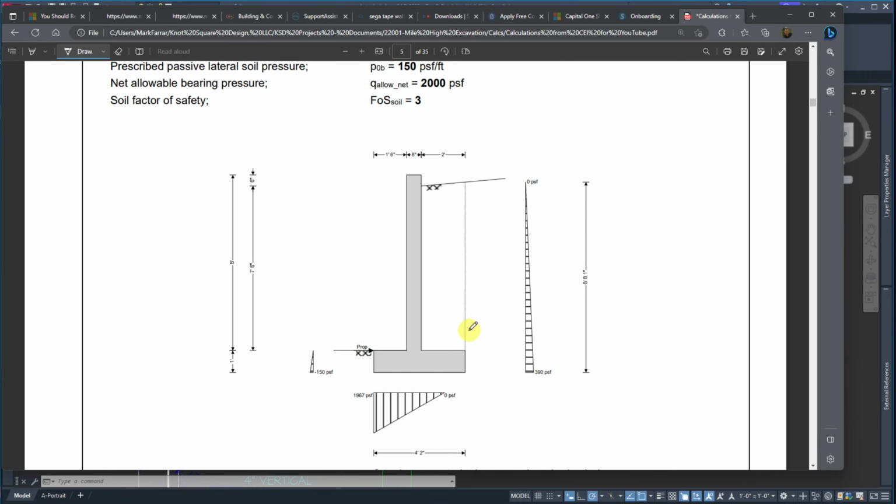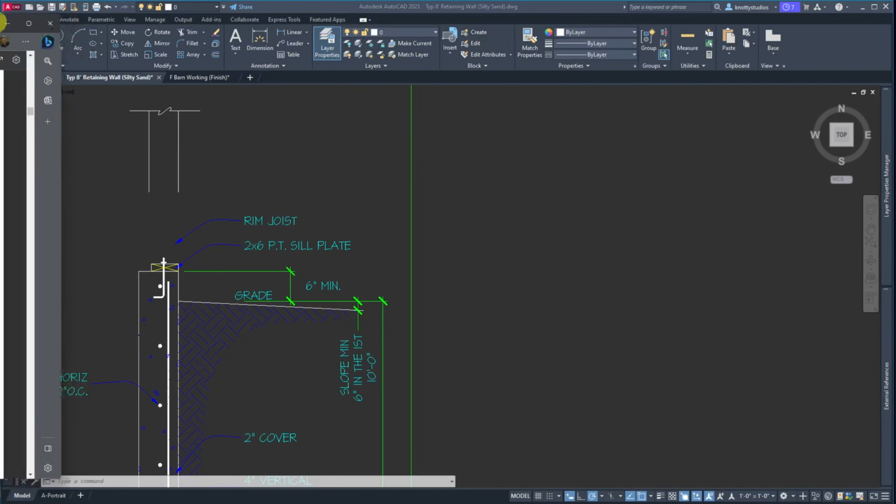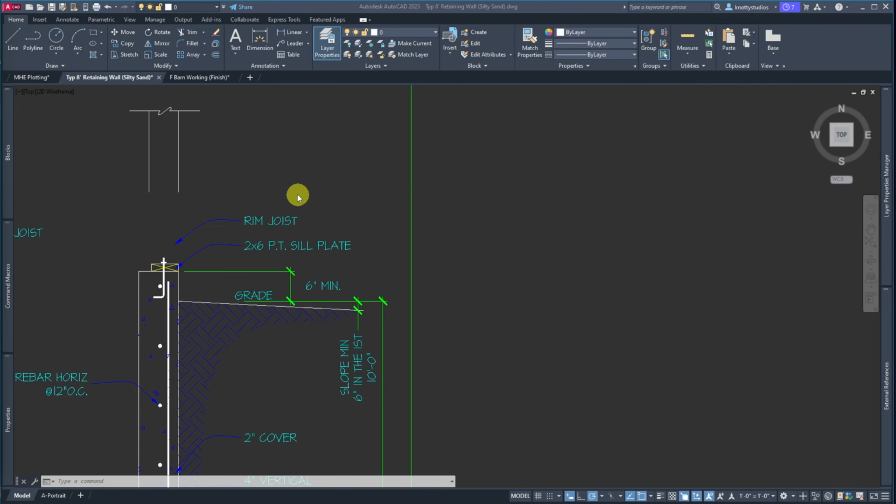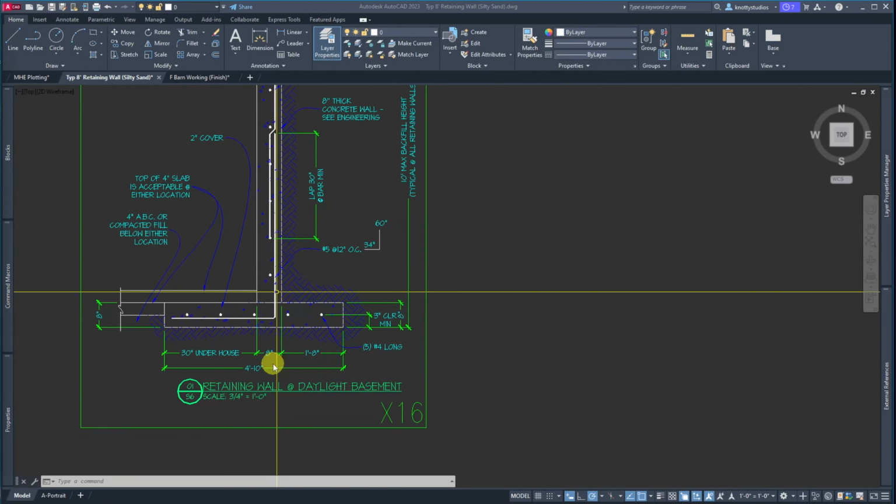And as you get to know a little bit about footings, a lot of times the bigger foot is under the dirt because that dirt is helping hold it from tipping over. So, depending on how much you're burying, that kind of thing gets into the design. Sometimes they'll put a cleat here, and that's to keep it from sliding if you're on a slope. So, what we've got with these general dimensions, we can start there and go down to the bottom.